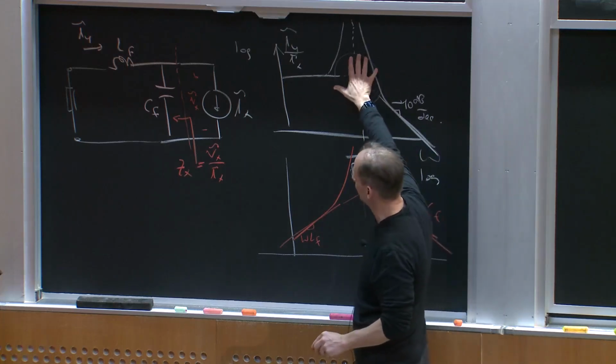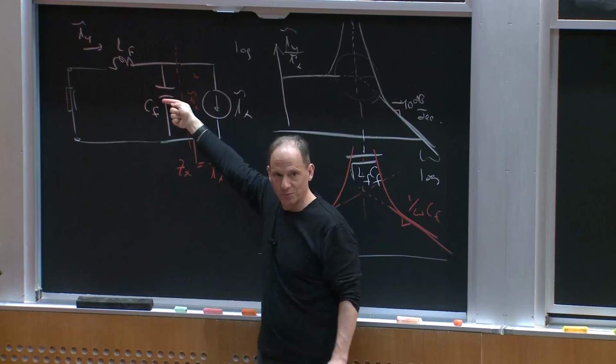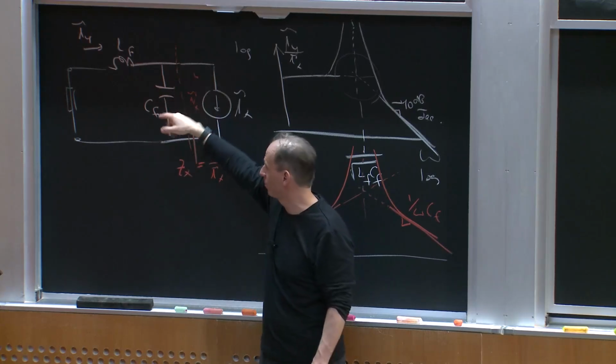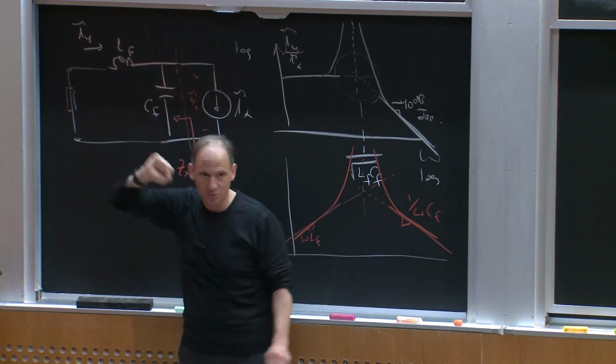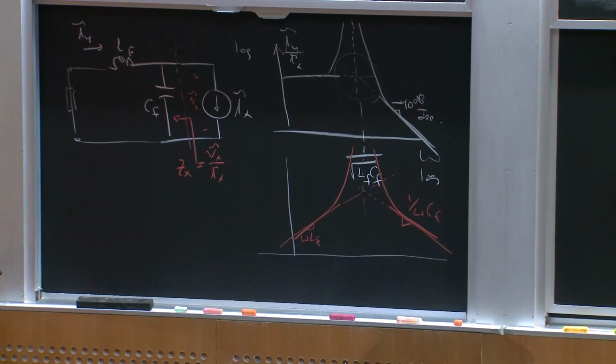That makes sense why this draws kind of high current. You're trying to draw current from an open circuit, and so you're going to get a lot of voltage ripple here and a lot of resulting current ripple back into the input. Okay, any questions about that?